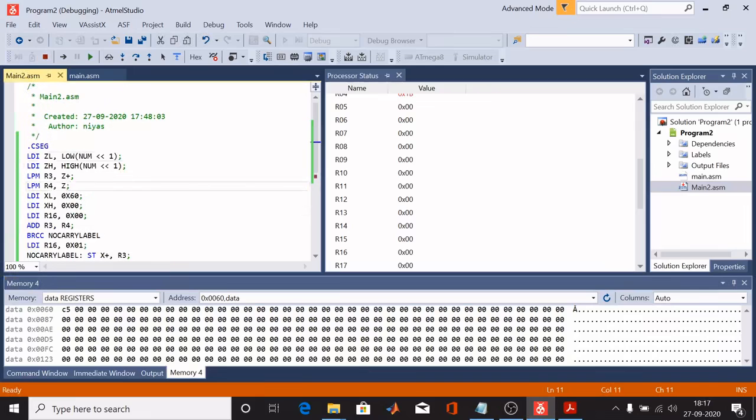Just wanted to mention these two instructions. The memory space, when we are defining the lookup table, is word addressable. But whenever we are loading the values, it is a byte addressable location. So to convert that, we are using these instructions. I hope you are clear with that, based on what sir would have mentioned in the class. That is the reason why we are converting the word addressable memory locations into byte addressable and taking the values.